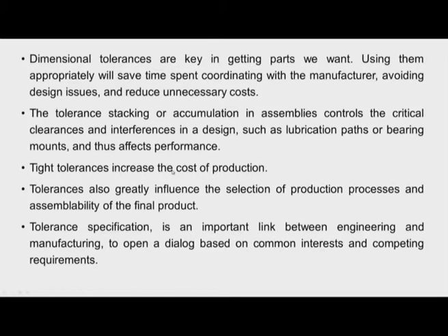And we should understand that tight tolerances will always increase the cost of production, and they will also influence the selection of production processes, and then the assemblability of the final product will also be affected. So the tolerance specification is an important link between engineering and manufacturing departments, to open a dialogue based on common interests and competing requirements.